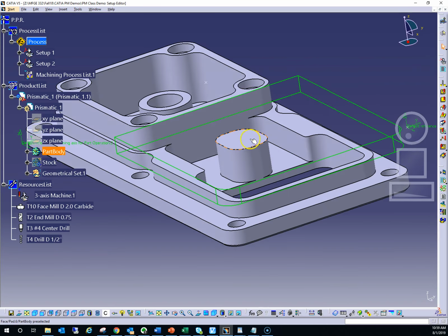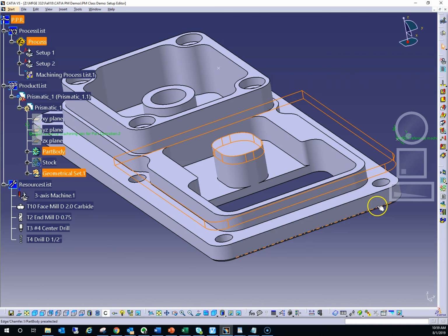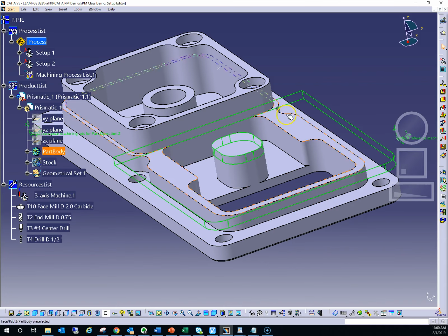So we're machining from the top of this down to this ledge here. So we can machine that also as an open pocket, with the one difference of course being that the top of this pad, or protrusion, now becomes an island that we have to avoid as we're removing this material.